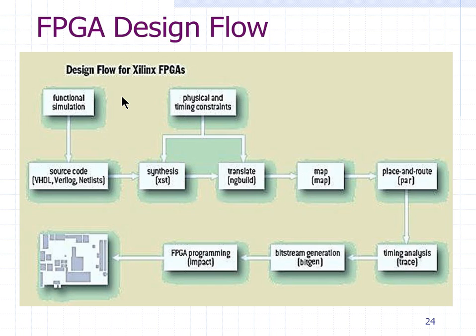I understand the flow. So this is a big-picture view of where Verilog fits. One more thing to understand is that this whole step, design, test bench creation, functional simulation, is all called verification of the design. You see a lot of positions, ASIC verification, FPGA verification. Why?